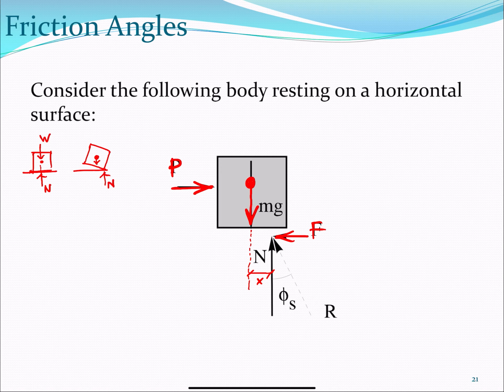So the fact that the normal force moves has to be accepted, right? Otherwise, how would things rock? There is always a point of contact. So the normal force can move and will move. The easiest way to visualize that is when the body is rocking. But you don't need the body to rock to see how the normal force needs to move.